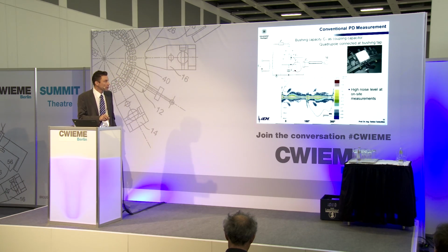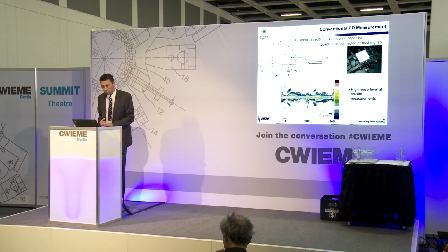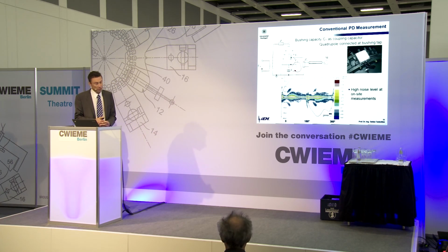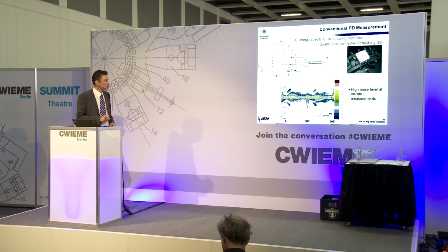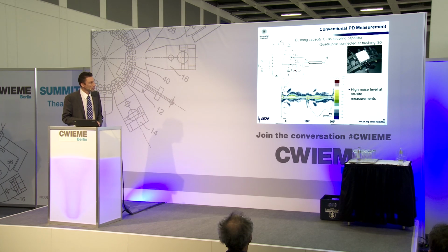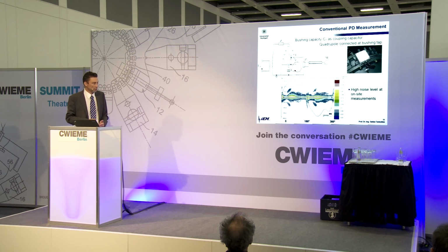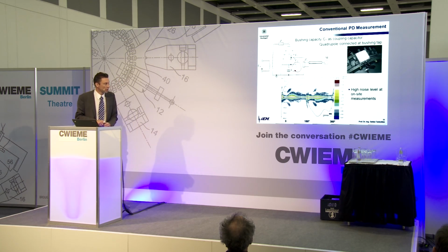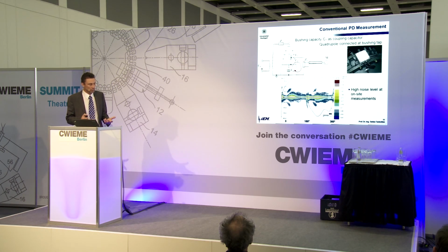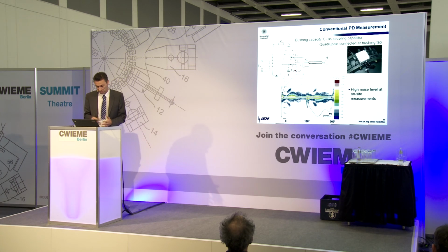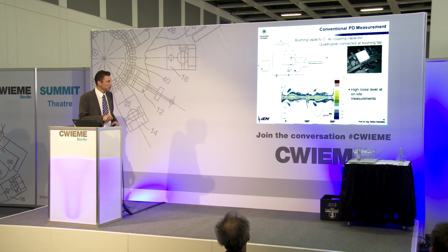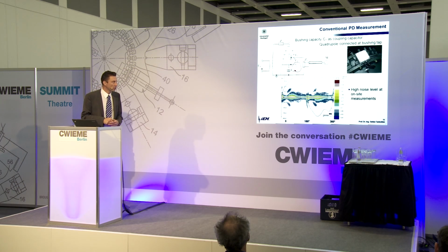So let's come back to the PD measurement. In this graph I show the equivalent circuit of a conventional PD measurement according to IEC 60270. Let's say you have here your transformer. The insulation system of the active part is shown here as a capacitor, which is connected via the bushing to a voltage generator. This can be, in case of an offline measurement, a separate voltage generator, or, in case of an online measurement, the electrical grid.